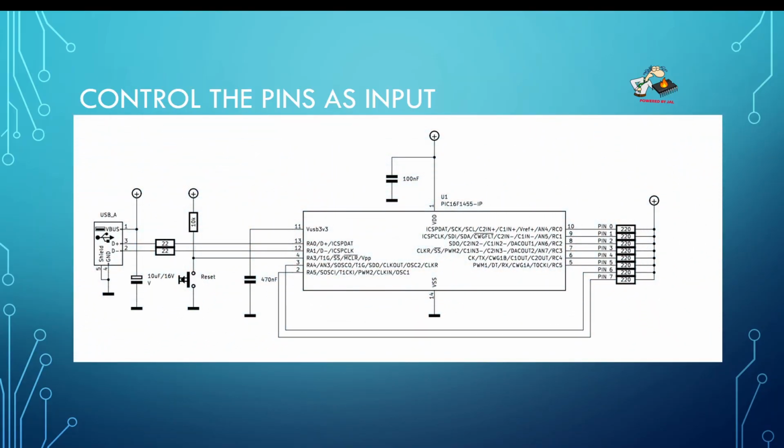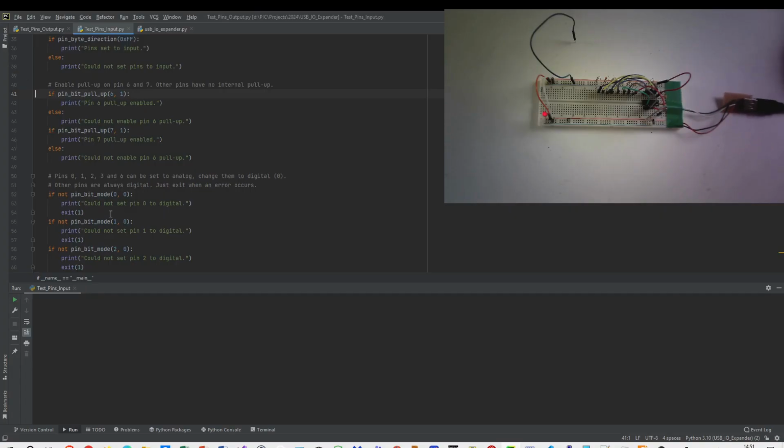Using the control pins as input, in this case I added pull-up resistors to the inputs because otherwise they're floating, and I'm using a wire which is connected to ground to make each pin low for a certain amount of time. So this is the test of the pins, but then we use them as inputs. All pins are connected to the VCC via a pull-up resistor.